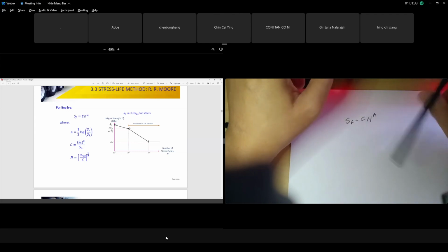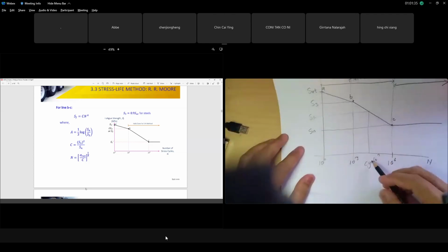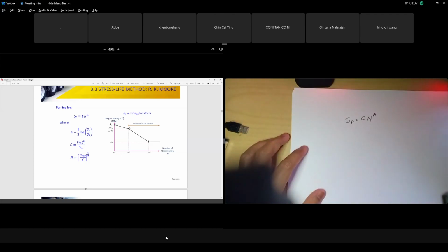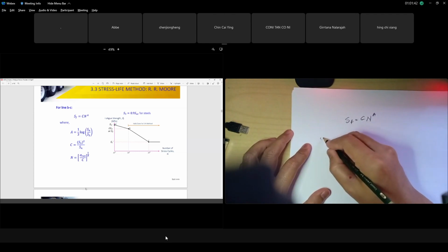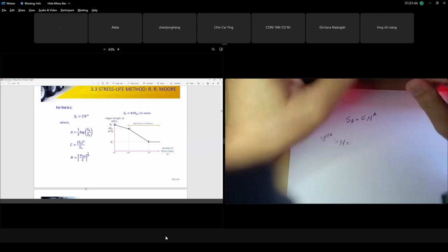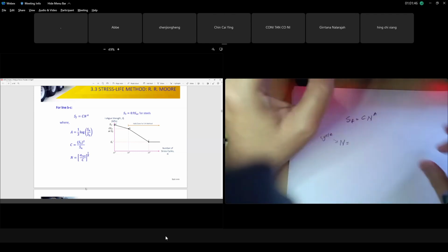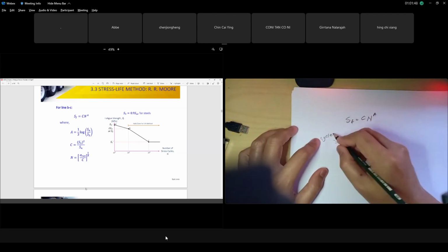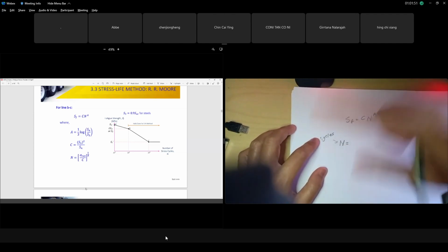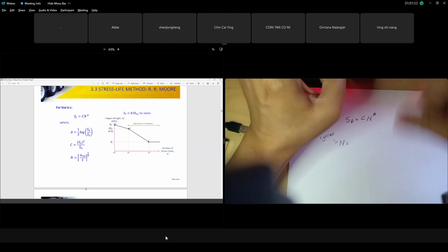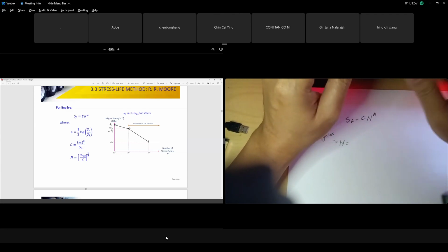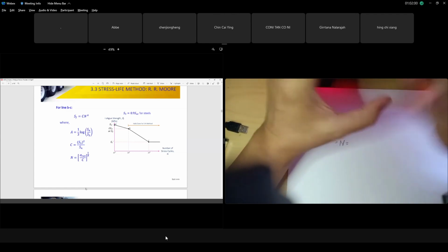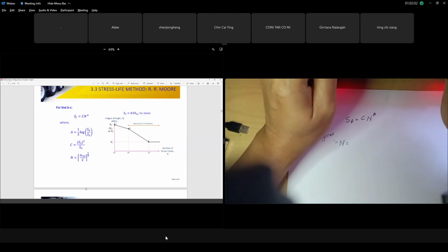Okay, but what we want to do is predict at what cycle it will fail. You can see the bottom equation. N is the cycle. At the point that you analyze on the shaft, how many cycles, how many revolutions, can you predict the failure? For how many revolutions it will fail. Understand? Sometimes we can predict. From that, we can design for how many cycles we need.